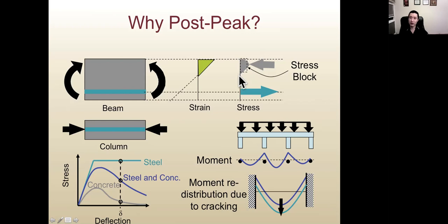As a result, when you do reinforced concrete design and calculate how much stress the beam can resist, we do not assume a triangle shape. We assume a rectangular shape. We will learn more about how to design reinforced concrete members in future classes, I think in 381 or 481.